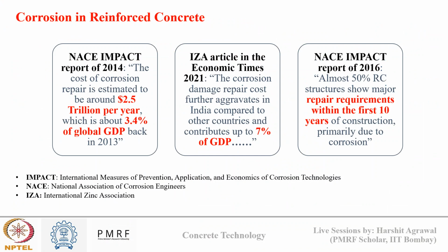Now the next topic that we'll discuss today and in the next session also will be concrete degradation due to corrosion. Most of the concrete degradation, maybe over 90% of the issues in practical application, arise due to corrosion of embedded steel reinforcement.